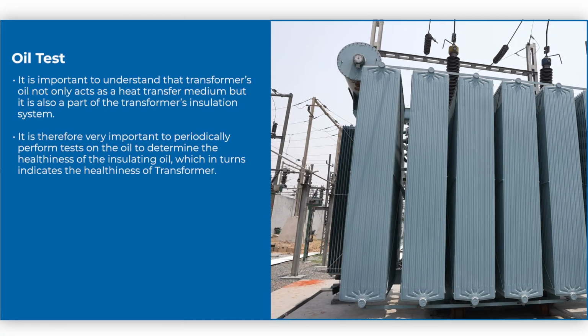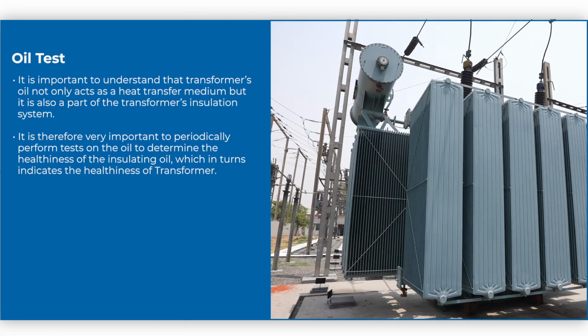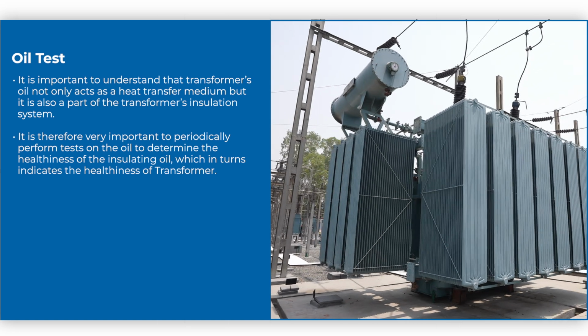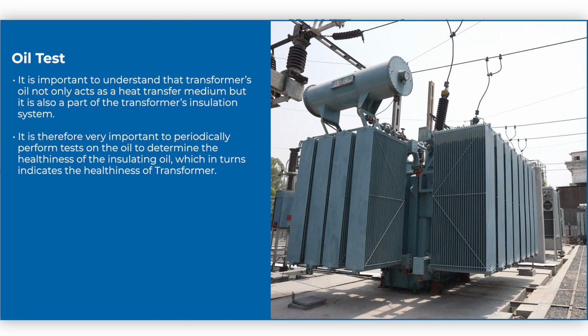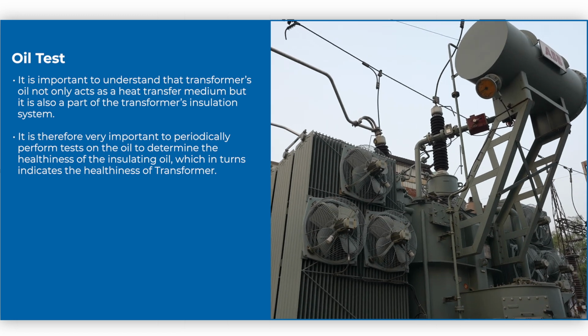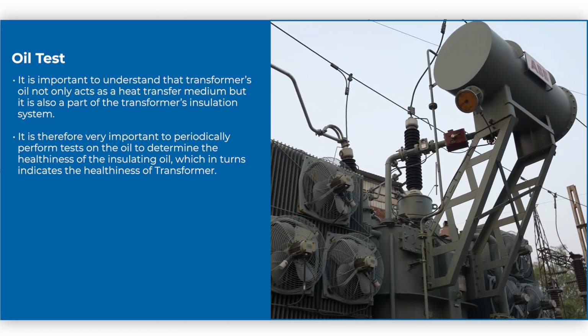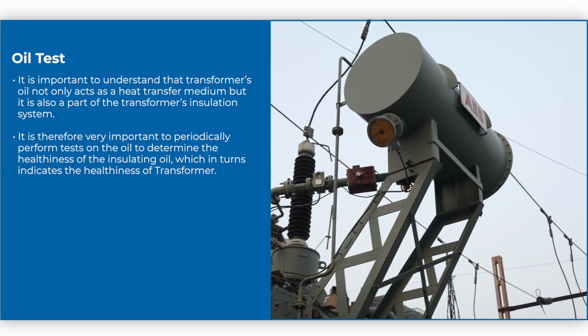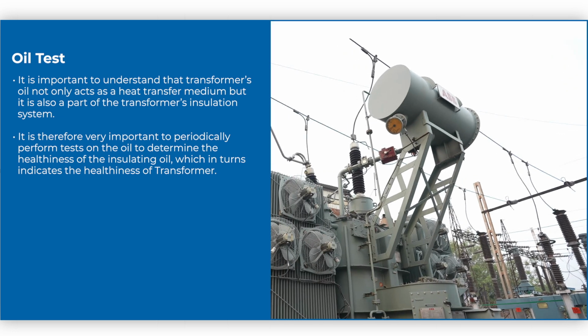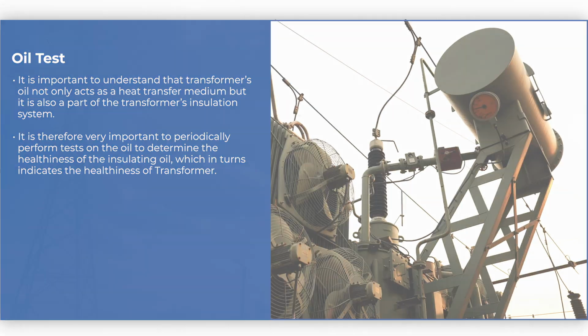Oil testing. It is important to understand that transformer oil not only acts as a heat transfer medium but is also a part of the transformer's insulation system. It is therefore very important to periodically perform tests on the oil to determine the healthiness of the insulating oil, which in turn indicates the healthiness of the transformer.